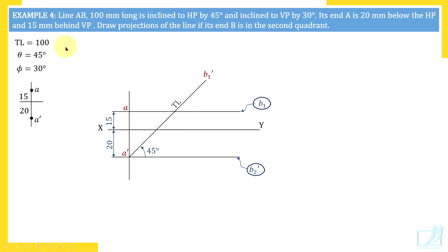Once you remember those 6 views and their lengths and inclinations, when you watch the data, you will immediately realize that the true length front view and true length top view can be drawn. So the top view with suffix 2 is the true length top view. So through A there are 3 top views. Out of those 3 top views, 2 have length PL.